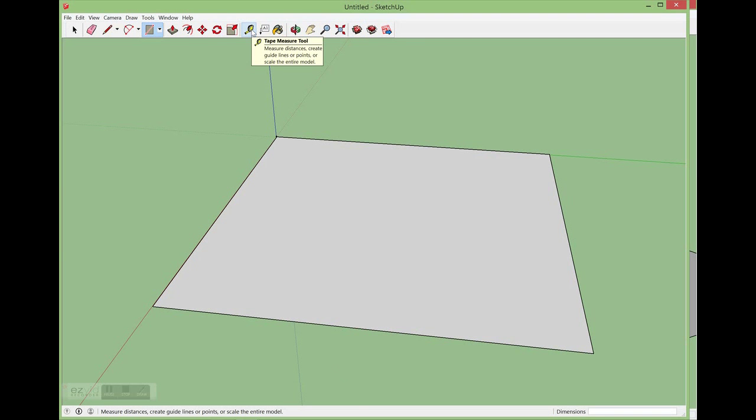I'm going to use the tape measure tool, clicking from the outside and then using the measure to measure around 165. So I'm just going to type in the number 165 and then feet and then press enter. I'm also going to do this for this side, 165 feet, and then enter. That way I know trucks can safely come in and out on both sides. I'll also do this on the third side, but can always change this later on if I decide. And I'm going to make this one maybe 150 feet, just a little shorter.